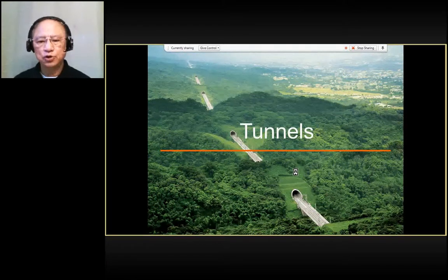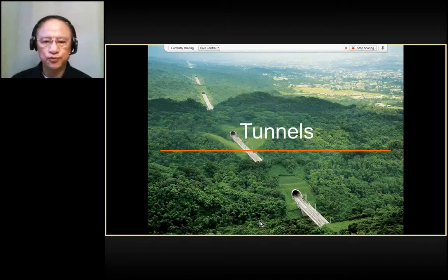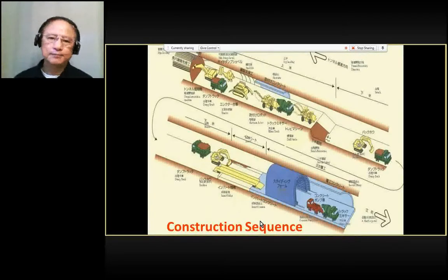high-speed rail tunnels have to be designed specially for releasing the pressure built up inside the tunnel. So it's the tunnel design which has to do with it, or reducing the aerodynamic pressure which builds up when the train enters it. So high-speed rail tunnels are generally bigger than most highway tunnels and so forth. Okay, the construction also has to be sequential in order to be efficient.